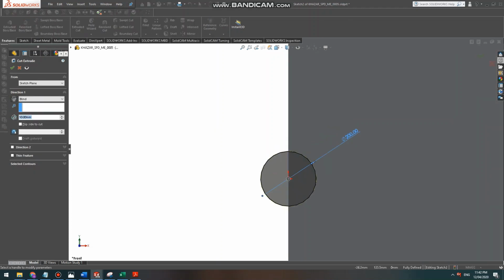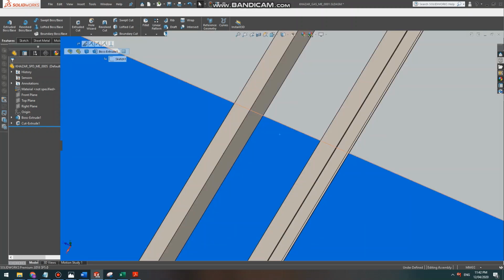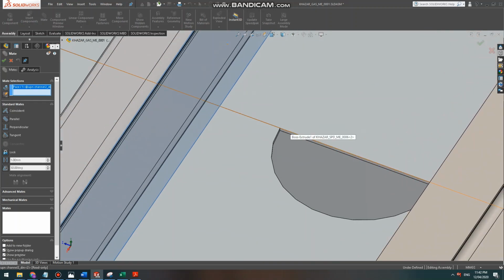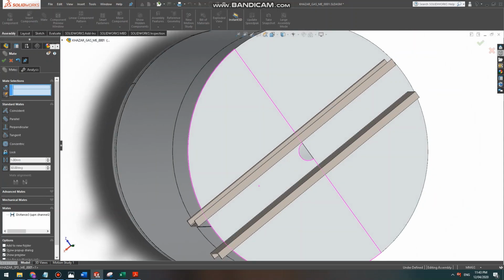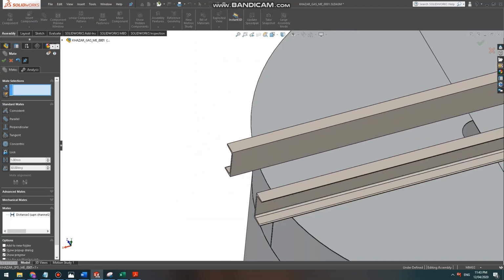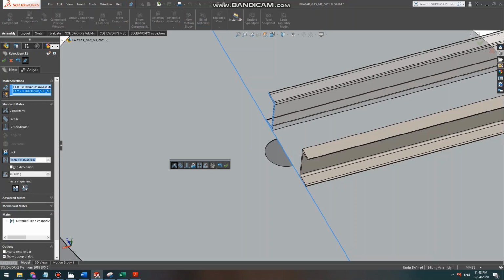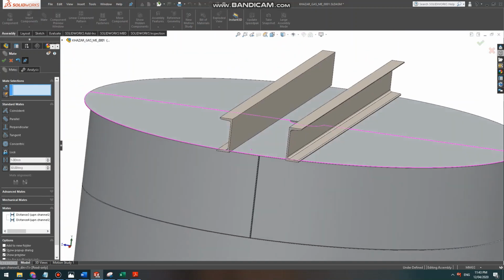We make a hole. Save it. It's a great help for us because we needed this hole to make it axis-centric, so we choose this point and we give distance. So it's 100 plus 160, so 160 minus 100, it's 60. That's it. Now it's settled, as you see. All we need is to give another distance, which is between this and this, which is 2700 divided by 2, and that perfectly finishes the job for us, as you see.